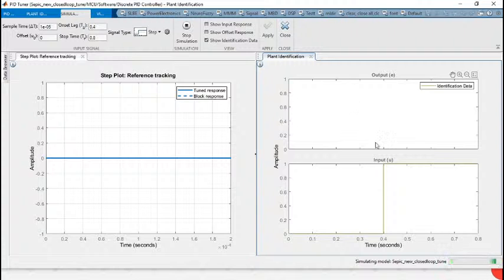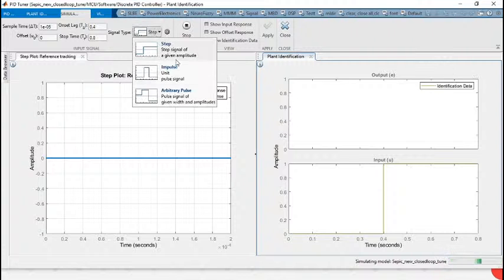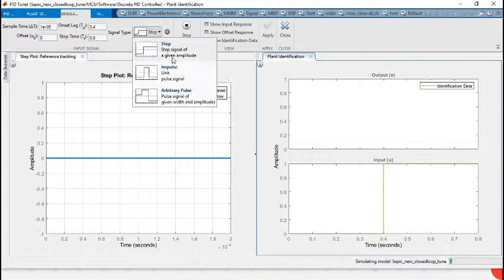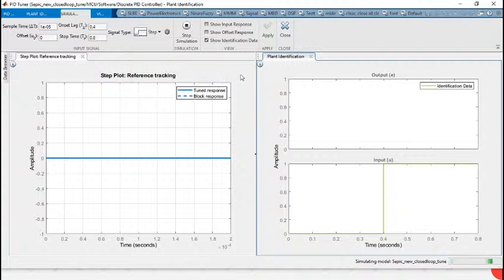One thing more we forgot to modify here. We had to provide the step time. What is the step time here? Here we have an option that this is the step response we are choosing. Input as a reference we are giving as a step response. Here we have to modify what the amplitude of that step will be. We forgot to provide that, right? So no problem.